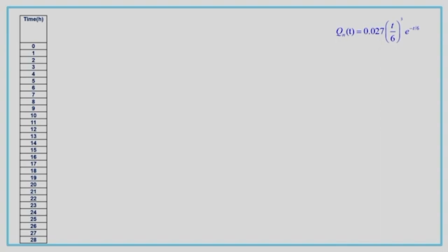Impulse input is acted on the catchment at time tau, and the response will be there after t minus tau. That will last for a certain time, and after that there will not be any response from the catchment. So we need to extend the values of t until we get a 0 ordinate for the IUH.